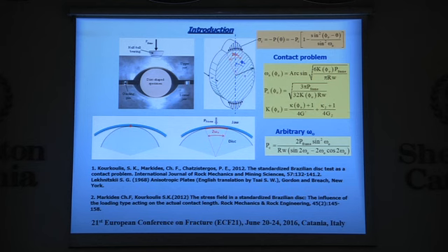Recall that when two cylindrical bodies, as here the curved jaw and the disk, come into contact, the compression along the interface is described by an elliptical law. Here we consider a parabolic one in order to avoid an extra approximation, since an elliptical law would lead to an elliptic integral. So we consider a statically equivalent distribution, very close to the elliptical one.